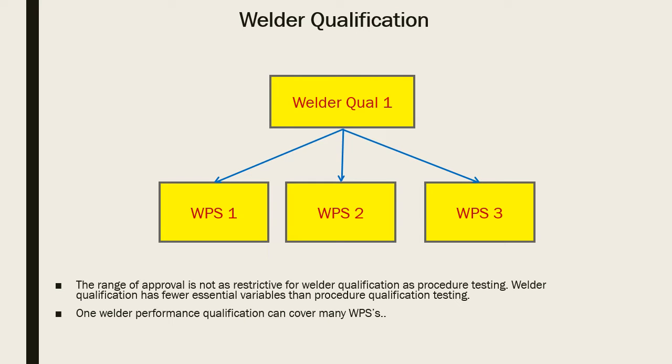Welder qualification, the range of approval is not as restrictive for welder qualification as for procedure testing. Welder qualification has fewer essential variables than procedure qualification testing. One welder performance qualification can cover many WPSs.